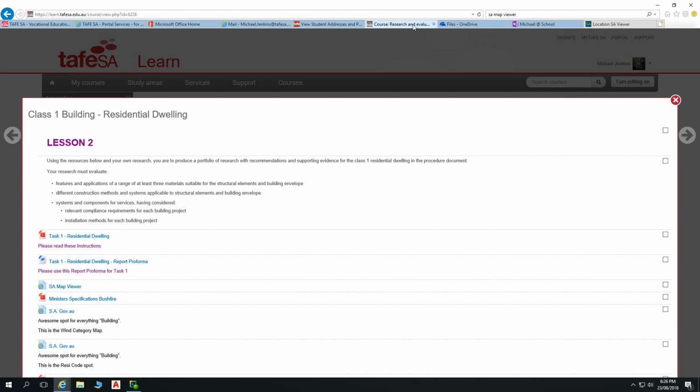So sheet roofing gives off a lot more radiant heat underneath than a tile roof will give off, because the transmittance of temperature through steel is much higher. The conductivity of steel is much greater than terracotta or concrete. Any other aspects to have a look at?